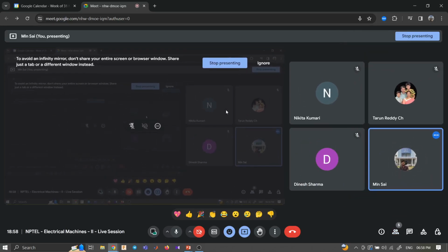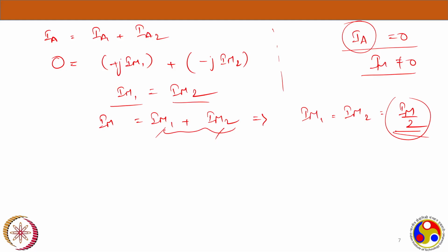Let's consider positive sequence first, and we will see the direction of the RMF produced there, and what is the speed produced there. Then we will see the negative sequence separately by reversing the phase sequence, and see how the direction of your RMF and the speed would be. Then we will see the resultant torque equation, and from there we will observe how exactly it is behaving, and when we club those two we will see the exact operation of a single phase induction machine.